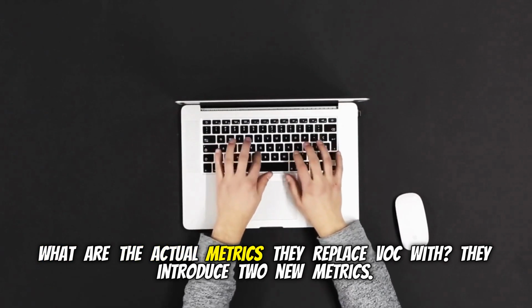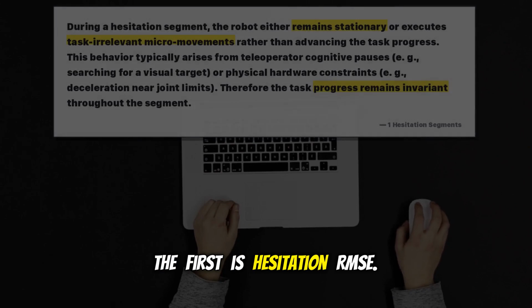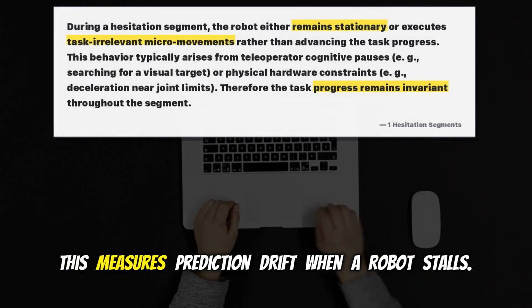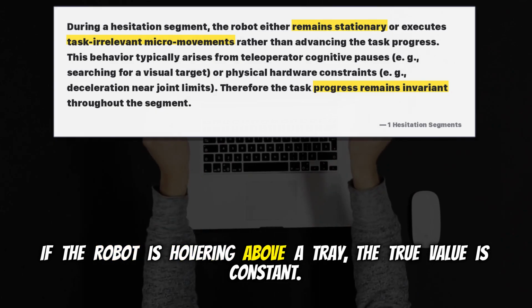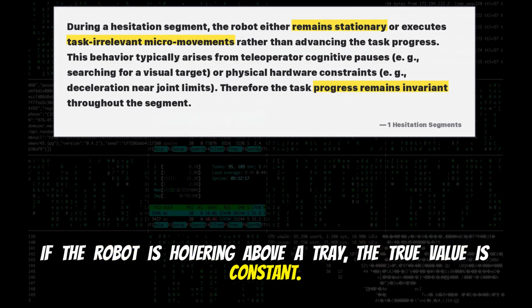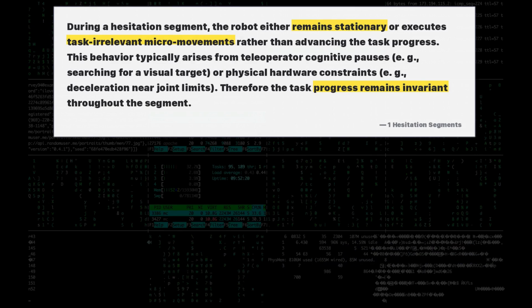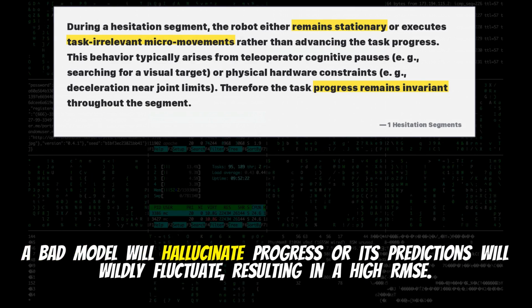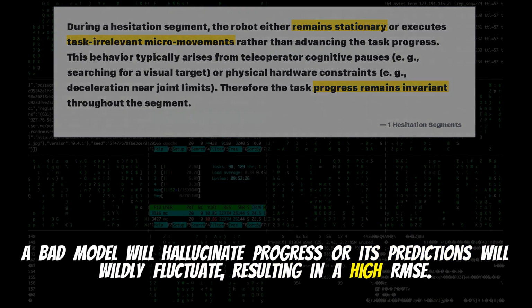What are the actual metrics they replace VOC with? They introduced 2 new metrics. The first is hesitation RMSE. This measures prediction drift when a robot stalls. Okay. If the robot is hovering above a tray, the true value is constant. A perfect model outputs a flat line and gets a root mean squared error of 0. A bad model will hallucinate progress, or its predictions will wildly fluctuate, resulting in a high RMSE.